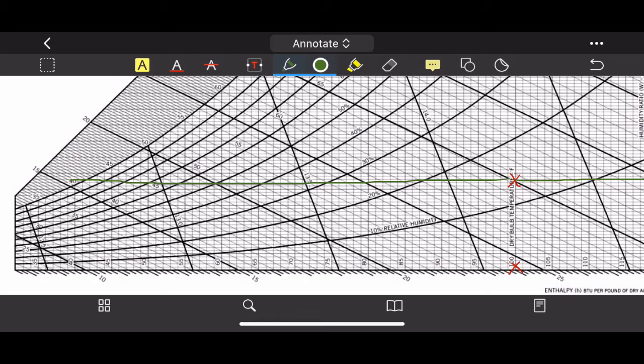Next, the relative humidity, which is given by this curvy line here. The curvy line is between 10 and 20 percent. You can use the difference on your ruler and find that X marks the spot, or I'll just take it as 13 percent, but you can use a ruler to be very exact. Okay, lastly, the specific volume, which is given by these lines.